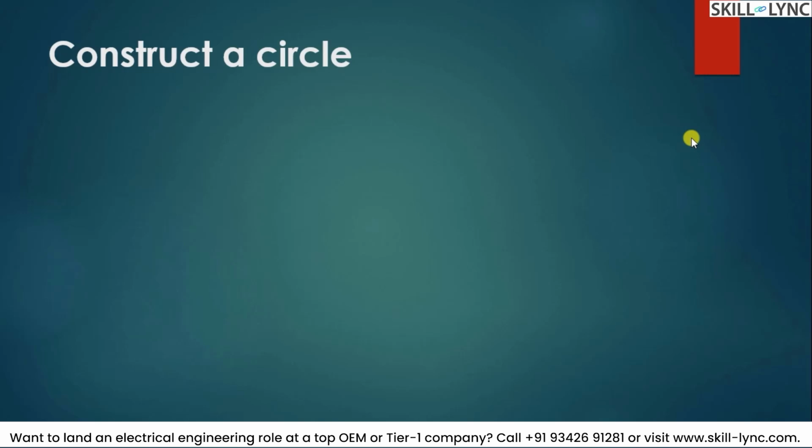Earlier in the macro we saw that we use an underscore command to invoke the circle command, followed by caret C to invoke the double cancel operation, and then execute this macro. Let us see how it is done in Lisp. But this is just to make you recall the steps that are involved in building a circle. Always, whatever you are replicating, as we talked about in the earlier session, we are replicating the steps that are done in a normal way in a programmatic, algorithmic way. So that is what we are doing here.